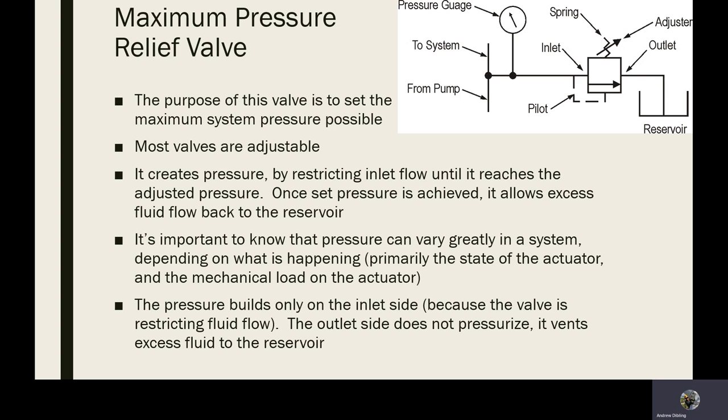I'm never going to say this too many times. You don't want your pressure relief valve set to the same or close to your operating pressure that you expect to get. Otherwise, you will have chattering and power loss. And yeah, it just won't work well. It's a safety device after all.